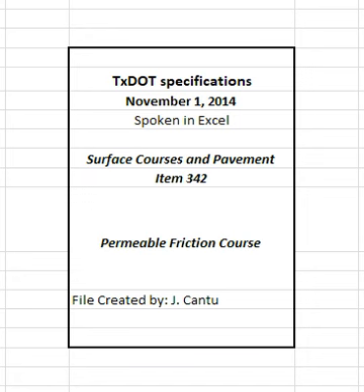4.7.3.1.3 Thermal camera. Take immediate corrective action to eliminate recurring moderate thermal segregation when a handheld thermal camera is used. Provide the engineer with the thermal profile of every sublot within 1 working day of the completion of each lot. Report the results of each thermal profile in accordance with Section 342.4.2, Reporting and Responsibilities. The engineer will use a handheld thermal camera to obtain a thermal profile at least once per project.